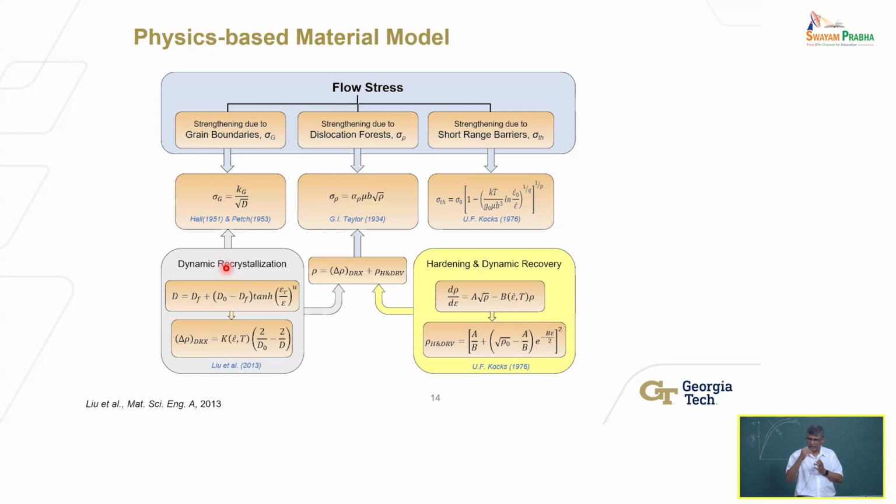As I continue heating, depending on the temperature, the dislocations I generated will relax. There'll be some recovery of the strain that you imposed. That's what happens when you anneal the material. Annealing is done after deformation, so you relax the strains. That's the recovery phenomenon.